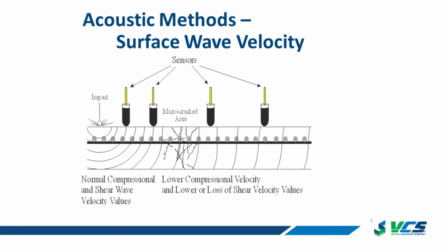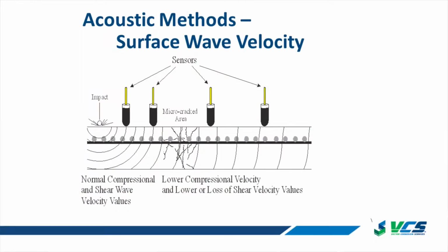What if we also have kind of cracking, vertical cracking? Impact echo is not as responsive to just simple cracks. It's more debonding, delamination, things of that name, more parallel activity. So if we use an array of sensors, not only are we monitoring the vibration of the stress wave in the vertical, but we can also look at the velocity of that wave between sensors. So we can look at velocity, and that's much greater effect due to cracking, vertical cracking. So if we have cracking between the sensors, that's going to affect that wave velocity.